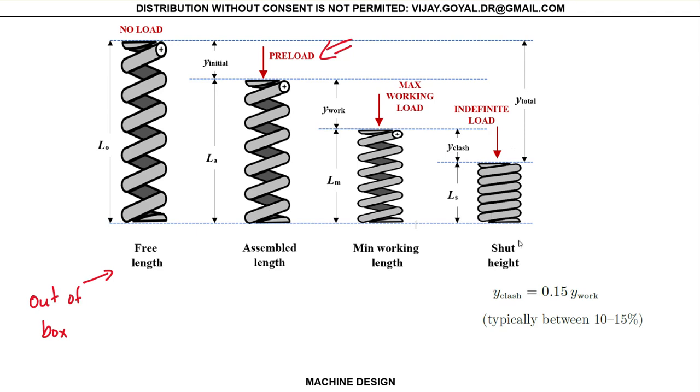And this is a very important design consideration because you don't want your coil to break when it actually slams together. So a typical value, we can take 0.15 for your design. However, it's very common to have 0.12, 12% as well. But for design purposes, 0.15 is good. Okay, and then obviously it's bound by 0.10 and as high as 0.15, but never go outside these values.